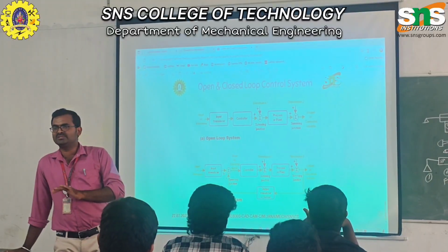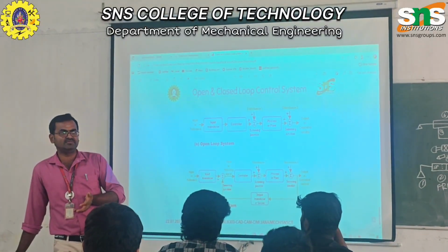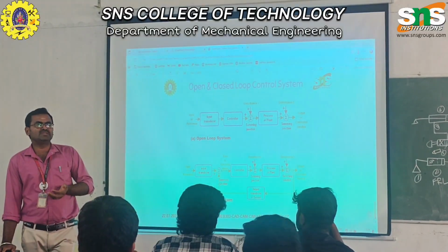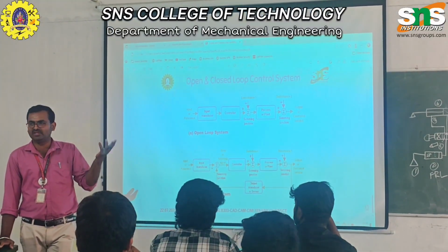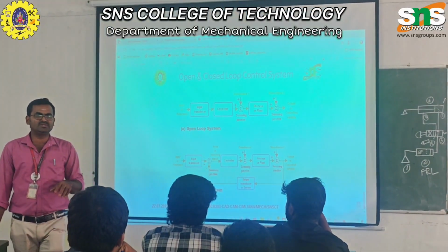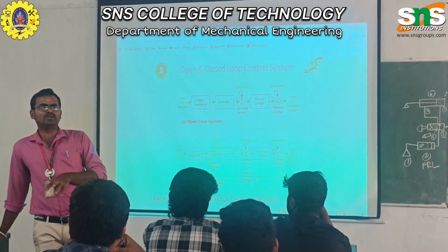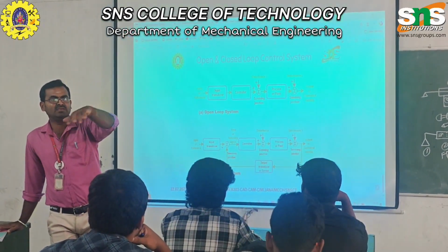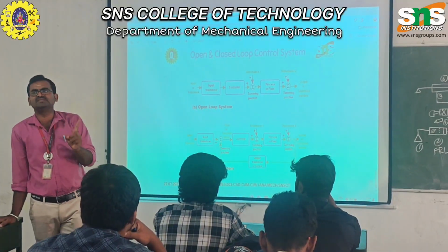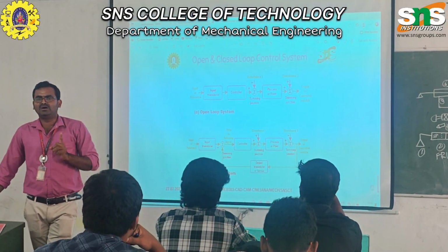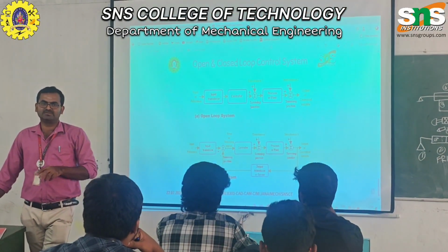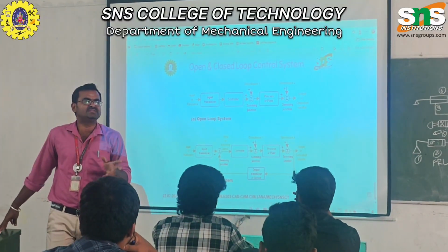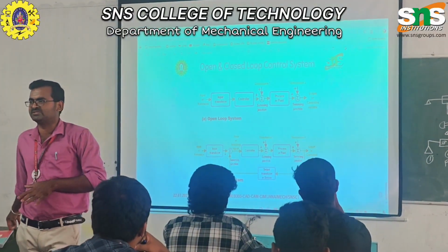After that, we use the computer assisted control system, which is computer numerical control, where computer keyboards are used to give the inputs, incorporated with the closed loop system. When we combine these CNC machines, all of them are controlled by one single computer system, known as the DNC system. This is also one of the best examples of a closed loop system.